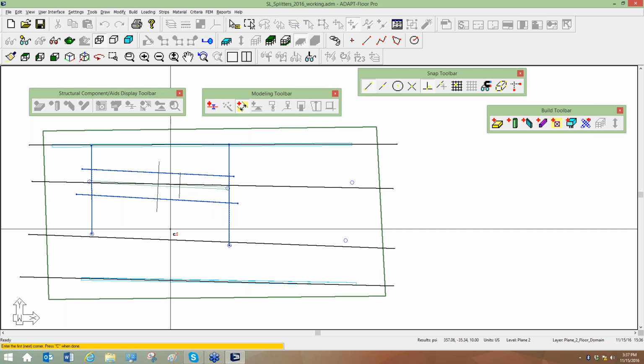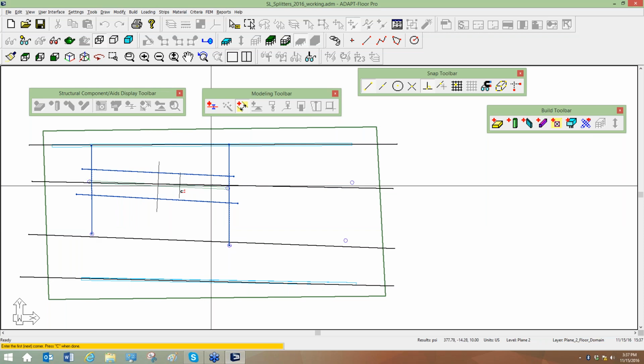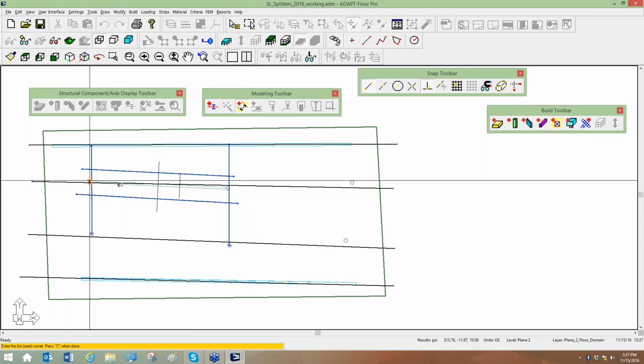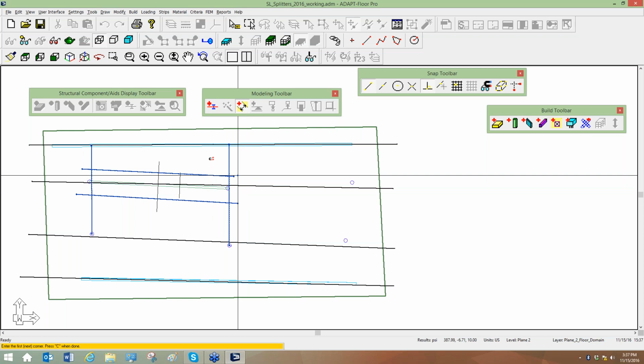It might be 2-span, 3-span, a single beam is its own entity inside of a more global two-way slab. What we're working on is a beam section manager. So the program would be able to identify beams. So any beam that is linked together becomes a continuous beam, or becomes a single beam in this case, and that beam has a section assigned to it.